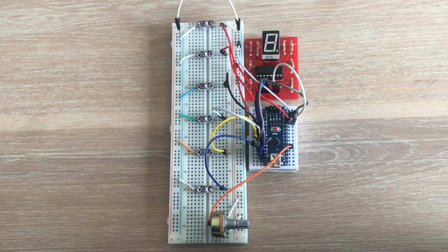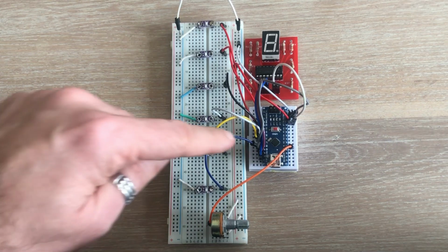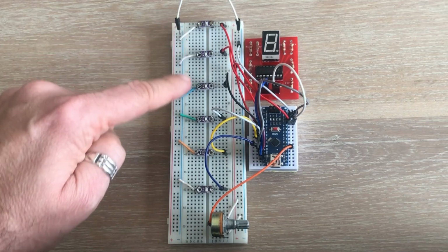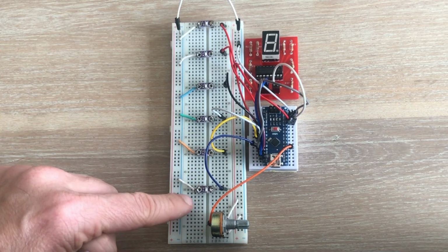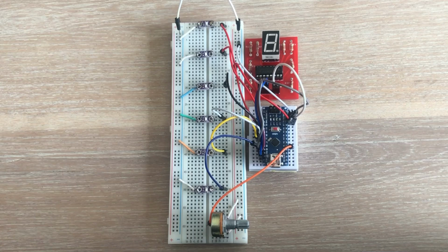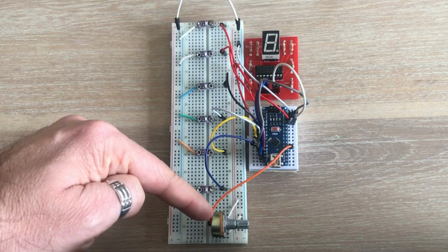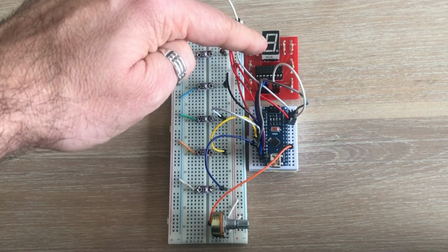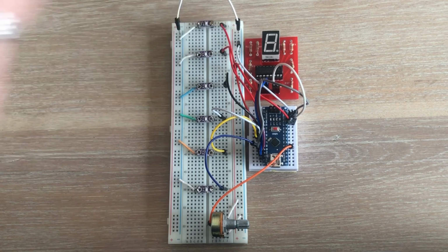To be able to do this, I built this simple Arduino circuit. In it, we are using an Arduino Nano and 6 LEDs. I'm using those LilyPad LEDs, which have built-in current limiting resistors, connecting minus of each LED to ground and plus of each LED to digital pins from D2 to D7. Then I have a potentiometer connected to one of the analog pins. And finally, I have a 7-segment display to track the current position of the potentiometer.